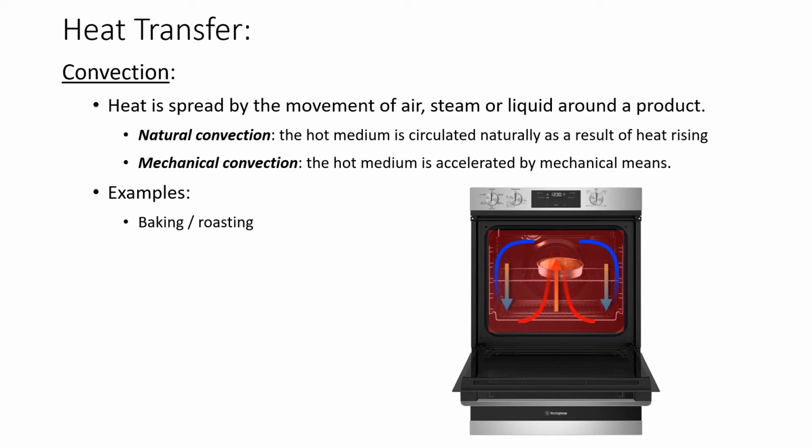This is a convection oven, so that would blow the air around, making it a much more even distribution of heat throughout the cabinet and more efficient. Generally speaking, when you're cooking with a convection oven versus a conventional oven, you can reduce your oven temperature by about 25 degrees Fahrenheit for the equivalent cooking temperature.